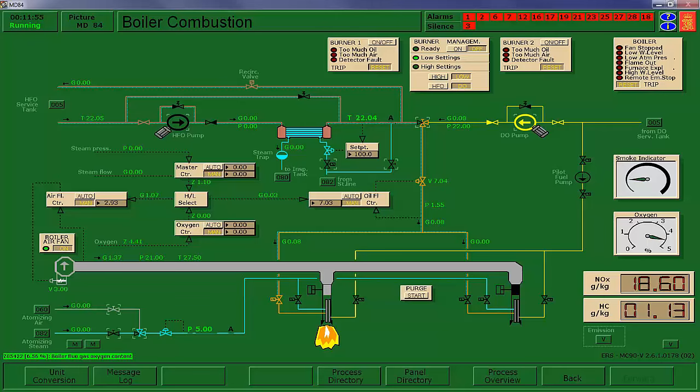We seem to have a stable flame. And I'm settling out somewhere around 3 or 4. Right now it's at 4% oxygen. Perfect. We've got a stable flame. We can now move on.